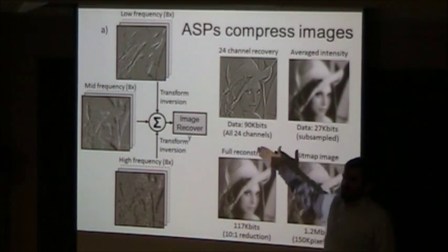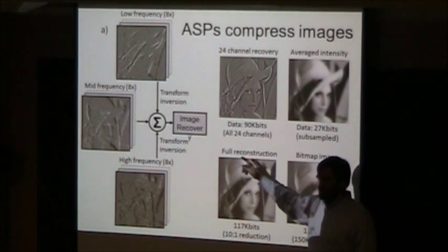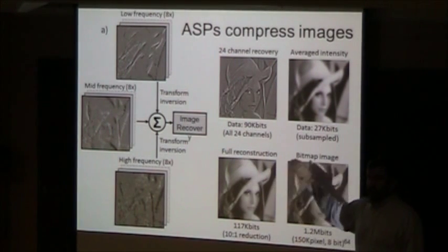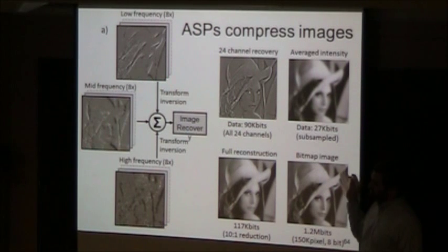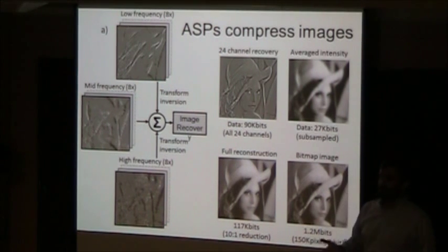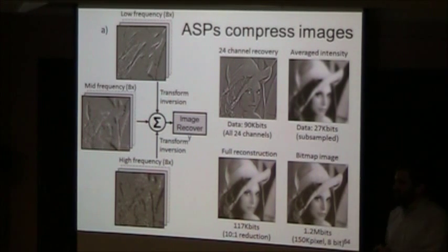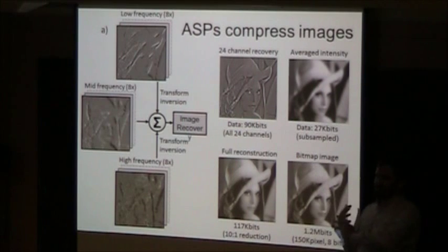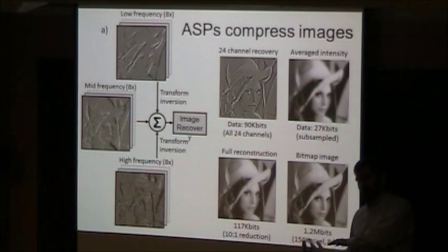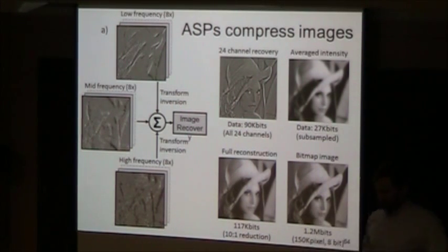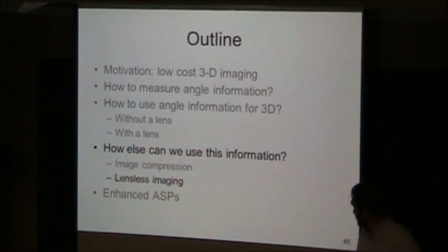But notice that all the hard math got done optically for free. And the rounding is called for by the analog-to-digital converter, which you have to do anyway. So you actually end up with potentially a system where the imager consumes less power than it would otherwise, but it's doing compression one way for free. So it's cool at least, right? Whether it's useful, we can argue about. I think we're sort of moving in the direction of how do we combine this with 3D to get a compressive 3D imager, and then that's pretty cool.